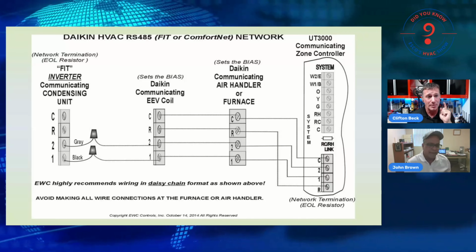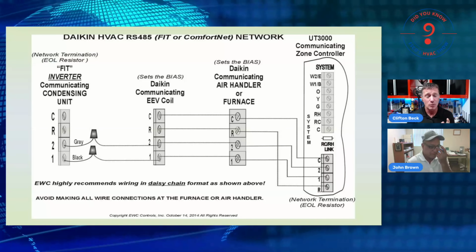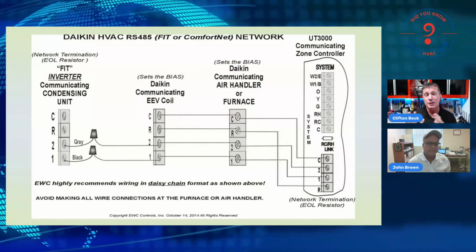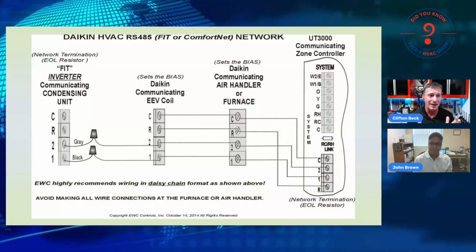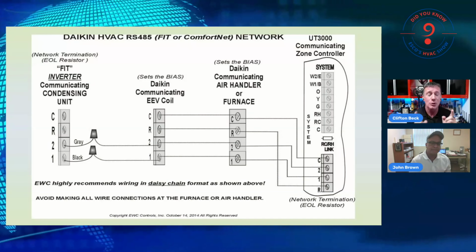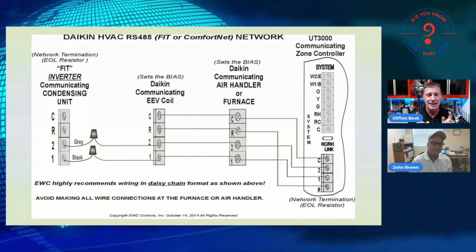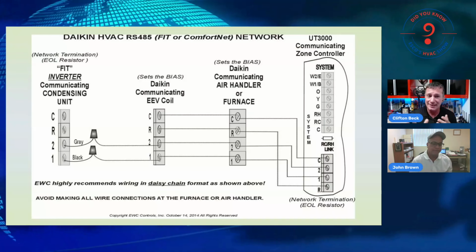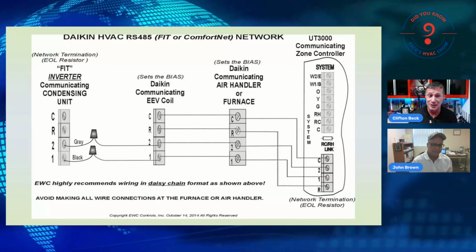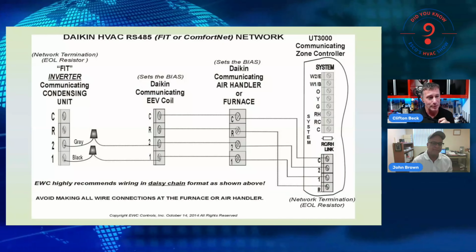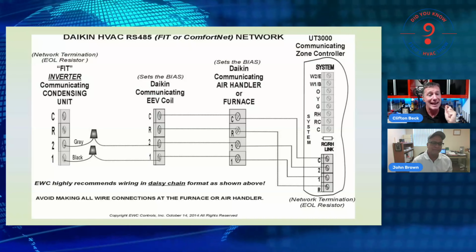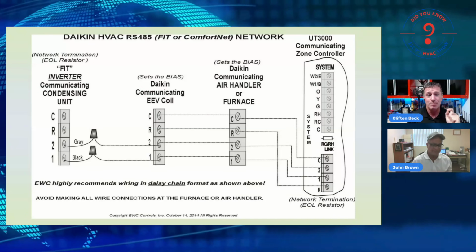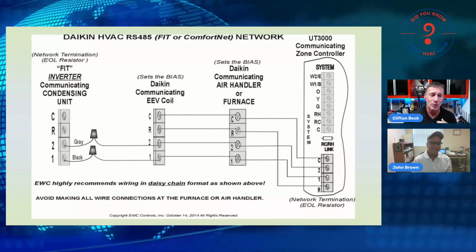And that's the thing to point out about that electronic expansion valve, that not everyone realizes that we are moving to electronic expansion valves to replace standard thermostatic expansion valves. But they are absolutely to our asset if we understand how they function. This particular one has two temperature thermistors, one on the inlet of the evaporator, one on the outlet, and now we can start using a pressure transducer, a suction pressure transducer.